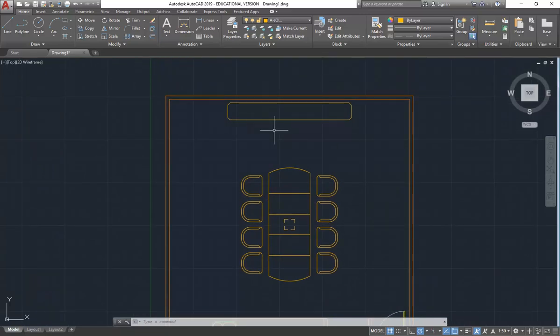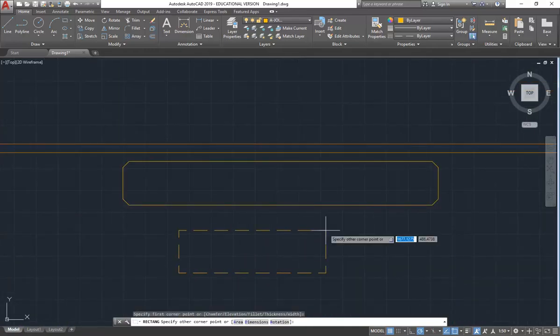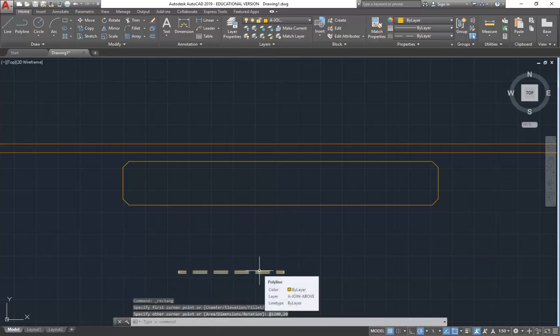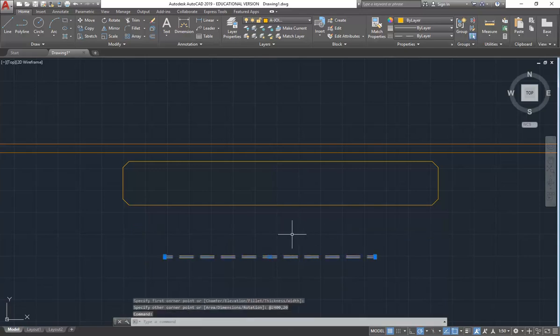So I'll do the same thing to put the projector in. It's going a bit faster, so I'll draw another rectangle anywhere. And again, I've forgotten the size. It's in here somewhere, I know, because I saw it. Here we go. It's 1200 across, comma, 20 mil the other way. That doesn't seem big enough. Oh, I know why, because they're giving you half the size. That doesn't make sense to me. I know in the notes that's what it says, but it should be the full size. So I'm going to just do that again, but make it 2400 by 20.